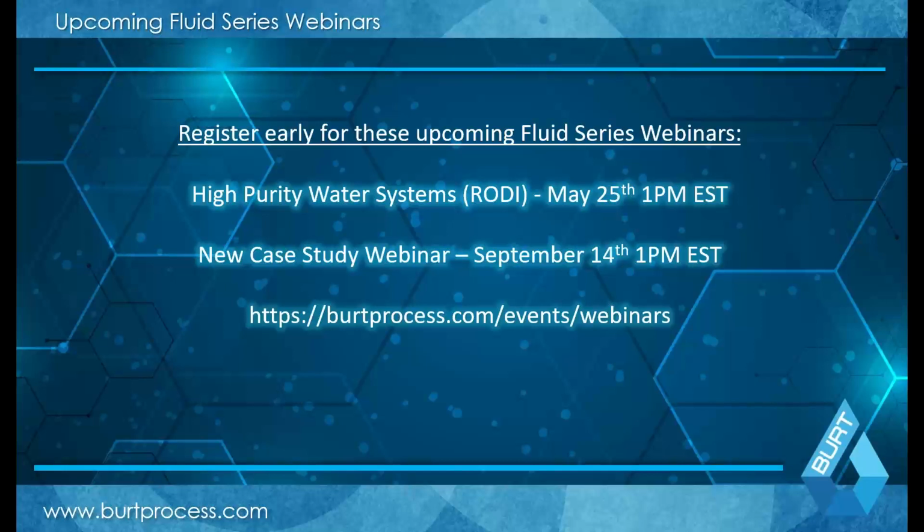In your effluent U-trap, for example, same situation. Now you have a concentrated pipe, for example, where you could be funneling that waste and it can build up. So yeah, if you have any application which is going to have very heavy solids or oils and greases coming into it, you typically want to have either a solids separator or an oil water separator upstream to really remove that before you get to your actual pH system.